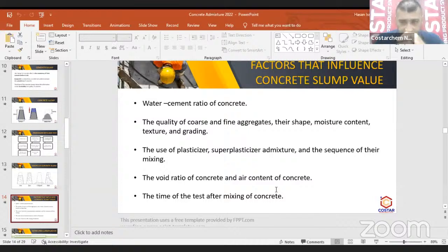Okay, so again, how much water your ingredients, such as gravel, sand, stone, or aggregate, will suck from your mix design. Your slump will also be affected. However, that's why we have a rule called SSD, surface saturated dryness. I'll repeat it again: SSD, surface saturated dryness.